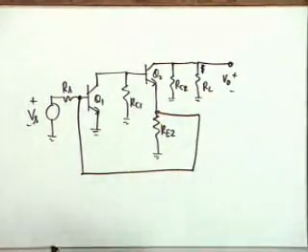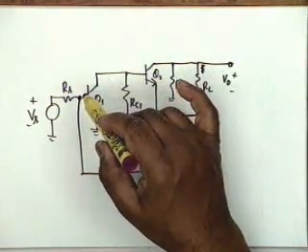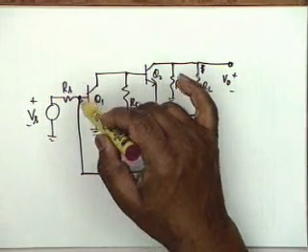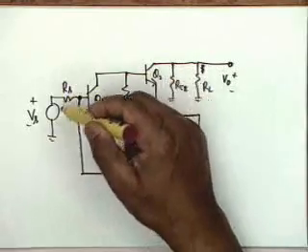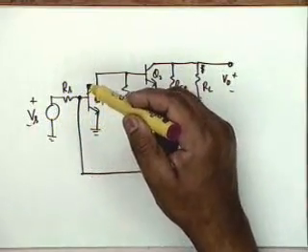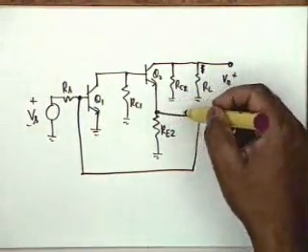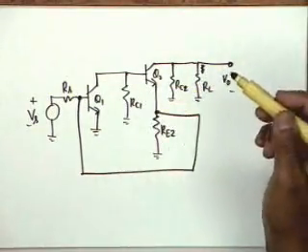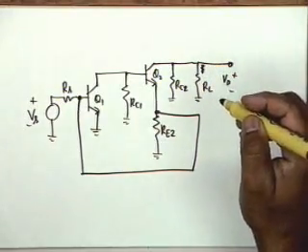Okay, there is also a chip that is available. Feedback is available like this. Now, tell me what kind of circuit is this? Obviously, this is a shunt connection, isn't that right? It comes in parallel, it draws away some current from the source. So it's a shunt connection. No quarrel about that. Now, what about this? It's a series because it is the current which is being sampled.